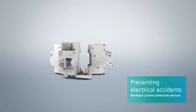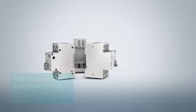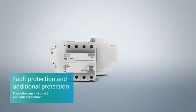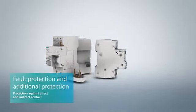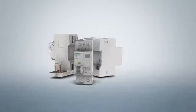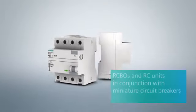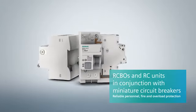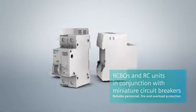Residual current protective devices have a proven track record dating back many years as effective means of protection. They give protection in the event of direct and indirect contact with voltage. They also offer supplementary protection against electrically ignited fires. Both RCBOs and RC units combined with miniature circuit breakers unite personnel, fire, and overload protection in one device.